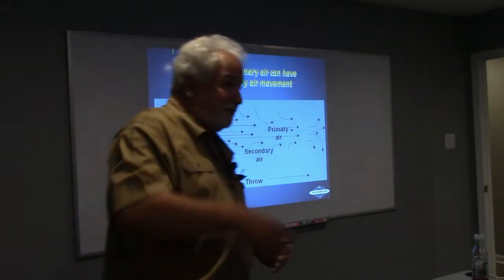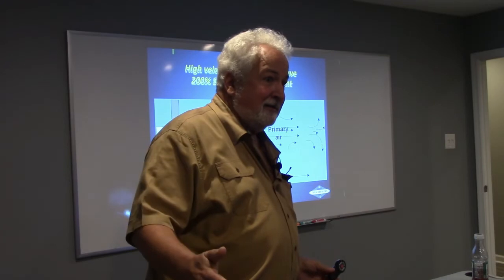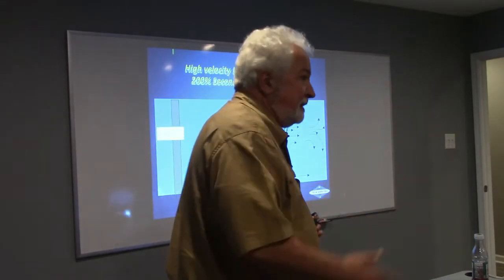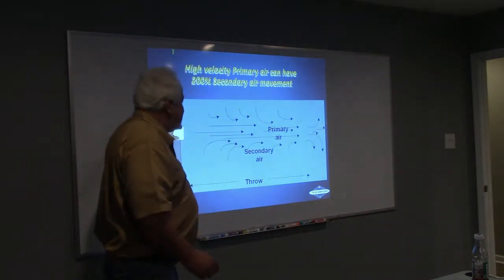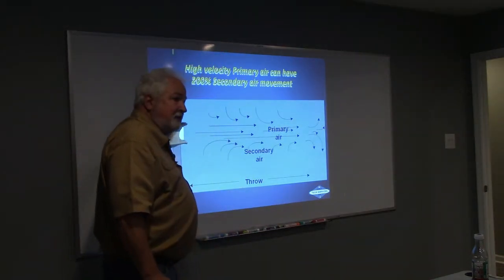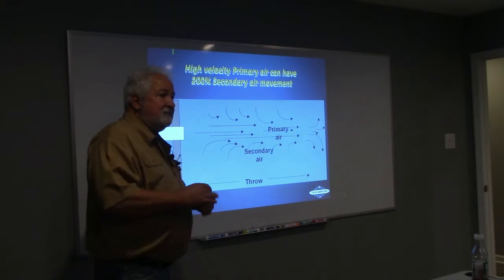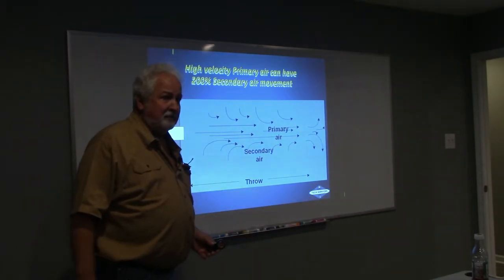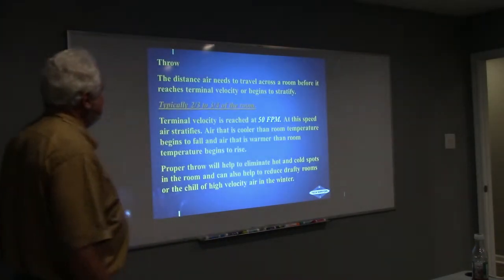So what does that secondary air feel like on a winter day? Drafty. That's why we have to get these ducts large enough on a heat pump, so as not to make the whole house feel drafty every time that blower comes on. Does that make sense? Cool.